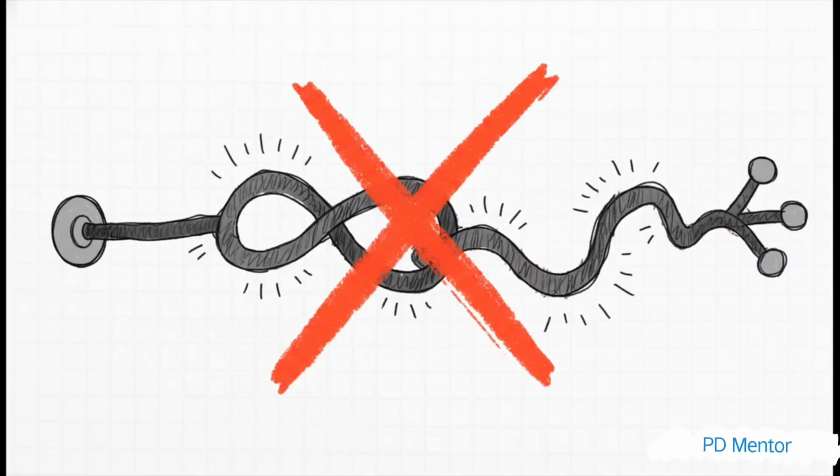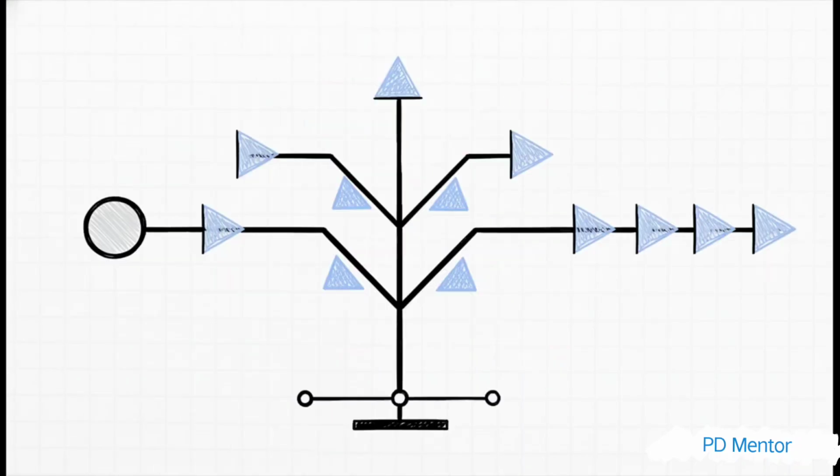Your first thought might be, hey, let's just use a bigger, fatter wire, right? But nope, that's not the solution. The real answer is way more clever. The secret sauce is building a tree made of what are called buffers. You can think of these buffers like little signal boosters, or maybe like relay runners in a race. They grab the signal, clean it up, give it a fresh push, and send it on to the next stop, making sure it arrives strong and on time.